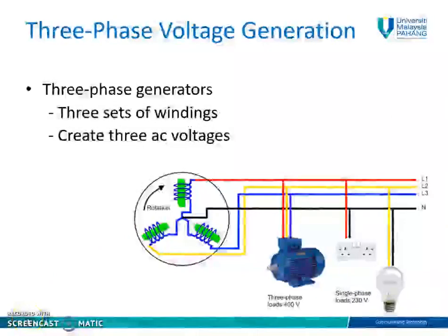A typical three-phase system consists of three voltage sources connected to loads by 3 or 4 wires or transmission lines. A three-phase system is equivalent to 3 single-phase circuits. The voltage source can be either Y-connected or delta-connected. The three-phase AC voltage can be used to run high-power electric loads, for example, 5 horsepower or loads of 400 volt. Okay, the single-phase is used to run only a small domestic load.